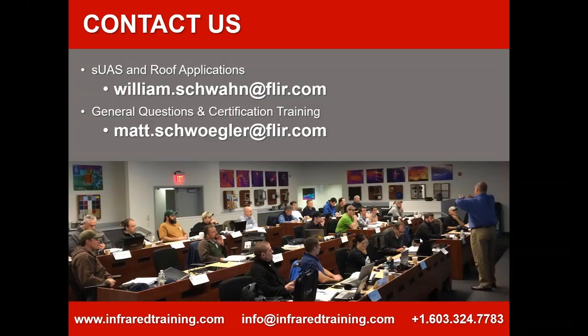Scott was asking about the ideal time to wait after solar loading for an sUAS inspection. Now, there are considerations for windows that we have, Bill, right? With the regulations that are out there. When do we go up and do an aerial IR scan of a roof? Right. Great question. Remember, FAA Part 107 says we have 30 minutes after civil sunset without what's called a daytime waiver. Yes, it sounds weird, but a night waiver actually allows us to fly at night. So you've got basically 30 minutes after civil sunset in order to not need an additional waiver. Remember, it doesn't always have to be after the sun has set. It just has to be with no solar loading on the roof. So I hope that one helps too.